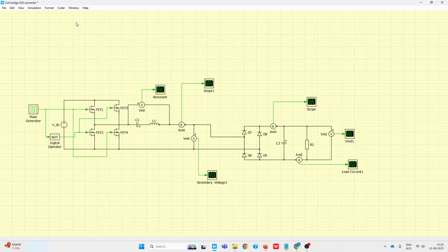To do this, first we will understand the concept of go to and from block. So let's take go to and from. If you press Control and U together, this search box comes. You click on the Goto signal, and then again you click on From. So this has come. We will use the Goto and From blocks.